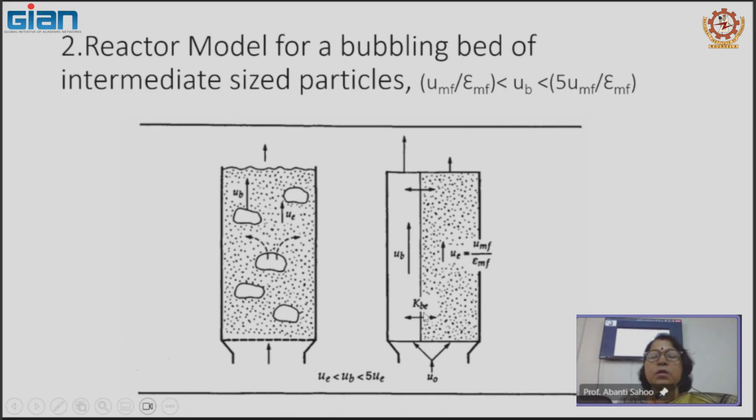So, here, bubble to cloud, and that is why, instead of forming the cloud, the gas immediately considers this gaseous reactant, which comes from the bottom, and uses the bubble as a shortcut path. It enters it and leaves at the top, because the gaseous reactant is moving faster than the bubble. So it leaves the top of the bubble, moves faster, and finally leaves the fluidized bed. Thus, it enters from the bottom of the bubble, as the gas moves faster, the gas speed is more.